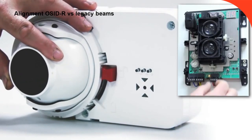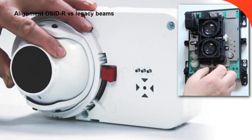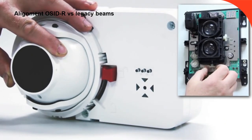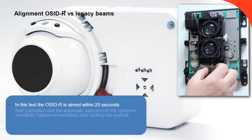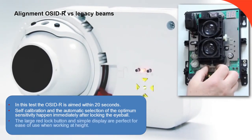OSID-R versus legacy beam devices. The OSID-R typically takes less than 60 seconds to align and auto-configure. A comparable reflective beam, the 6500 or 1224 in this case, can take many times as long and is much less intuitive, also requiring special tools to operate the micro switches and the addition of a lens cover which must be secured by screws before the configuration process can be started.